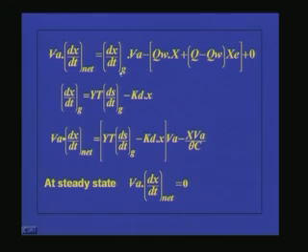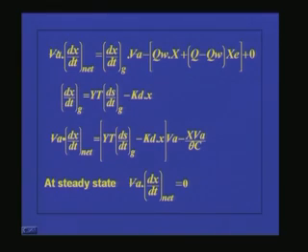When we discussed the biokinetic parameters, we saw that (dx/dt)/x is the specific growth rate. If you multiply that with X, we get (dx/dt) growth equal to Y into (dx/dt) utilization minus kd into X. That means the yield coefficient into dx/dt, minus the endogenous decay constant kd into whatever biomass is present in the system.